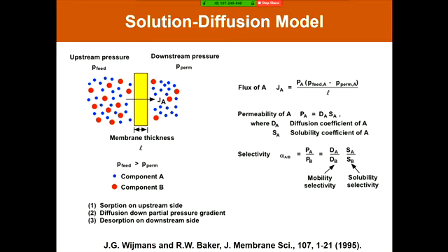And in polymeric membranes, the rate limiting step in how gases, for example, diffuse through membranes is the thermally stimulated segmental motions of the polymer dynamics that are ceaselessly opening and closing small gaps or free volume elements in the polymer matrix that allow the gas molecules to execute diffusion steps. And so it is the polymer segmental motion that gates the diffusion of penetrants through these polymers.